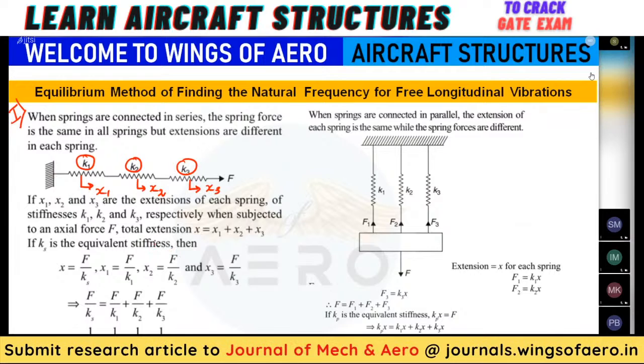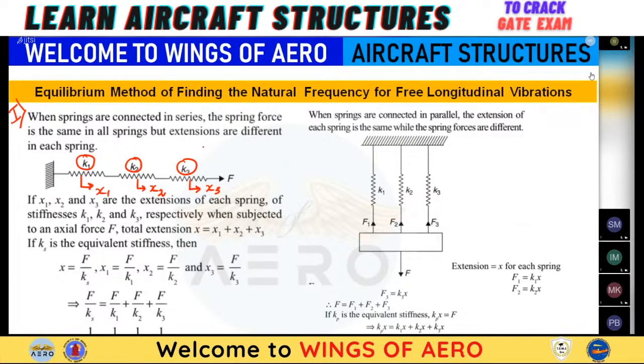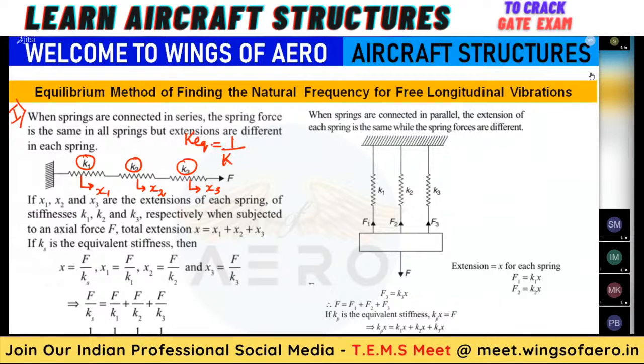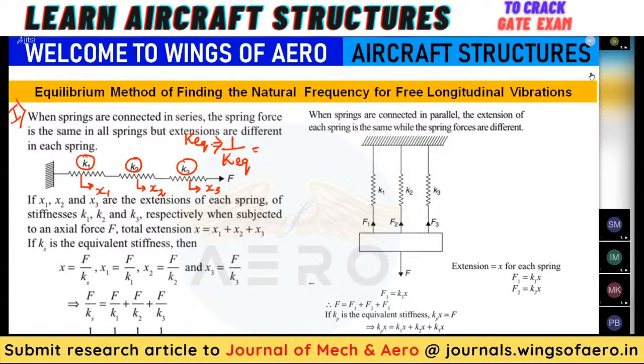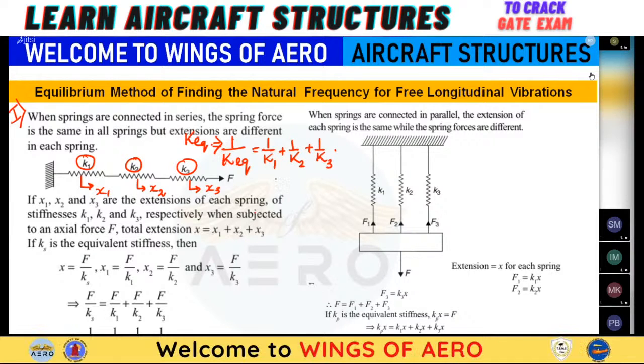Now, derivation is not important, but when the springs are in series, to find the equivalent stiffness, we can write K suffix equivalent like this: 1 by K equivalent equals 1 by K1 plus 1 by K2 plus 1 by K3. Now we need to solve this.